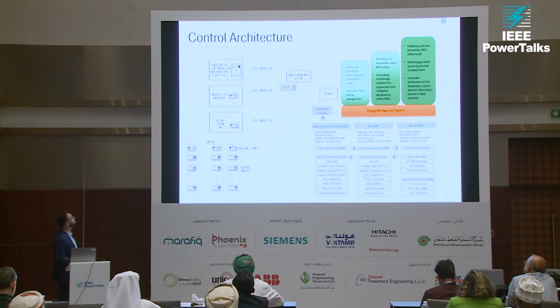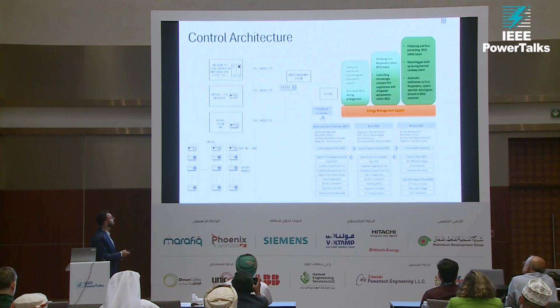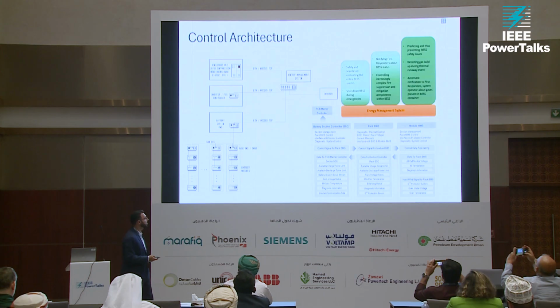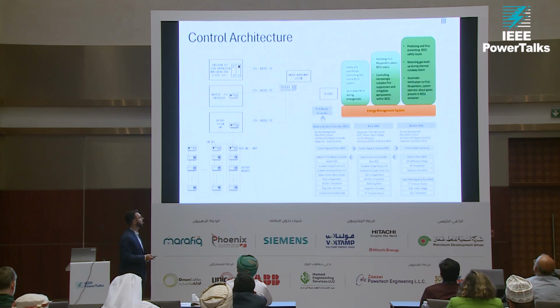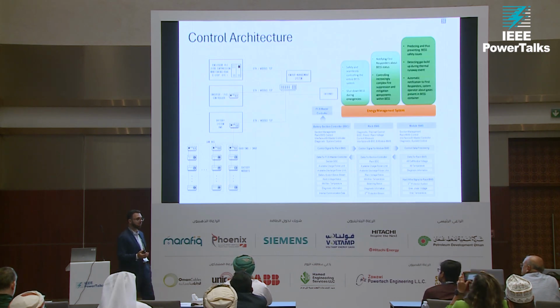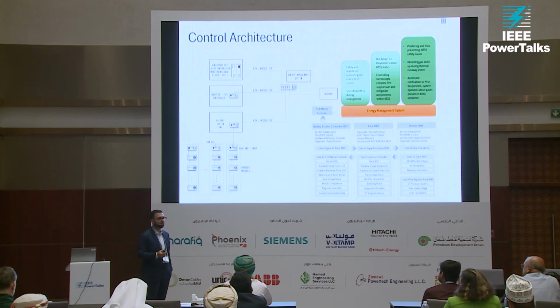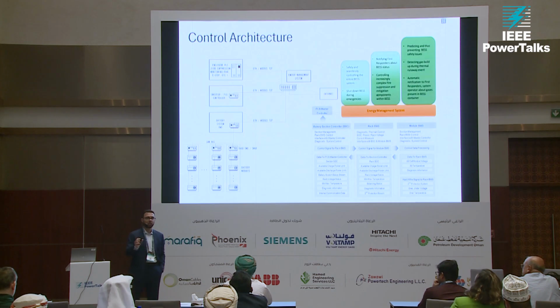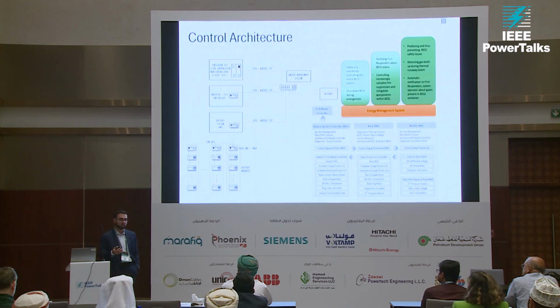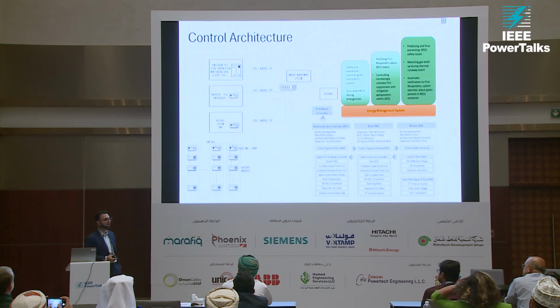Okay. So, control architecture. We talked about the BMS. For the sake of time, I'm not going to spend a lot of time on this, but each of the BMS levels has its job. The level 1 BMS gets temperature and voltage data from the system and helps with protection. Some systems do measure current, amperage. It's very hard to do that on a cell level, because these are very small readings. A typical battery cell is about 3.5, 3.6 volts, so trying to measure that on thousands of cells gets pretty complicated. Imagine doing it for an amperage reading.